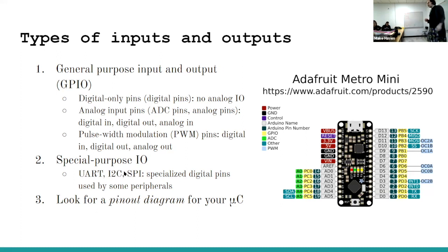Specifically, it's I2C. So if I have an I2C device, then it's going to have an SDA pin and an SCL pin on it, and I will have to connect those to the matching SDA pin and SCL pin on my microcontroller, which is advanced, and I'm not expecting you to remember any of this now.